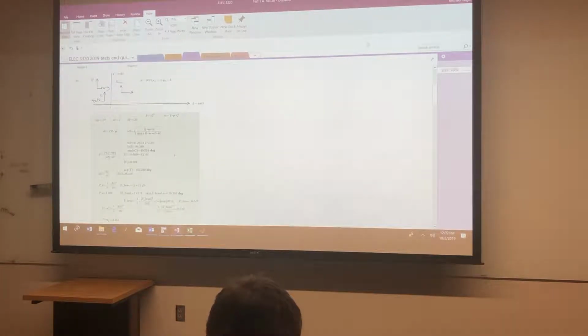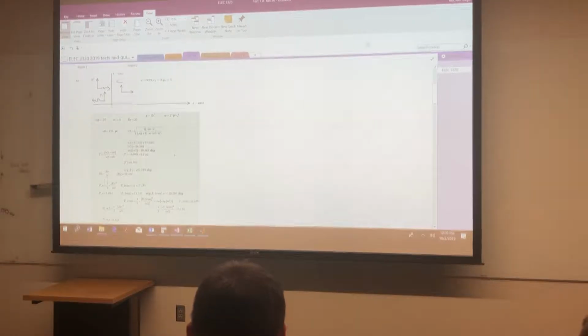I'm using just capital T here because the gamma function that I have, if I put it in there, it's a lot of additional keys I've got to press. So this is the reflection coefficient. Now, I know the incident wave times the reflection coefficient is the reflected wave's magnitude. And I only cared about magnitude, not phase. Therefore, if I take the reflected wave divided by gamma, I get the incident wave. So that's my incident field right there. Just magnitude is all I care about.